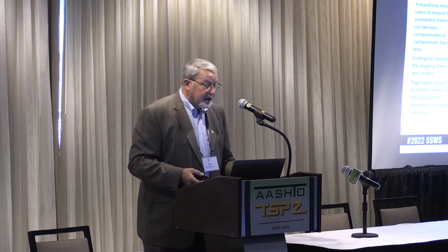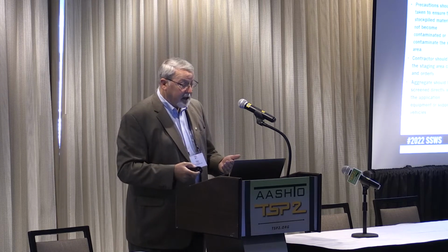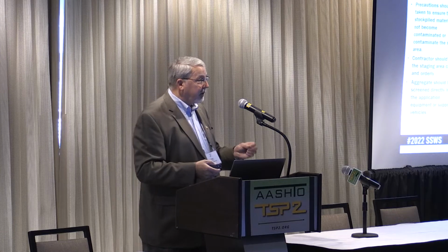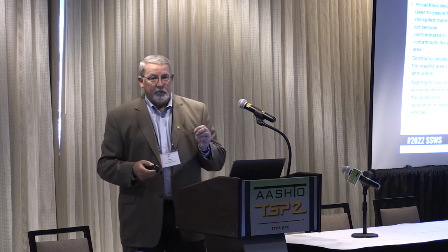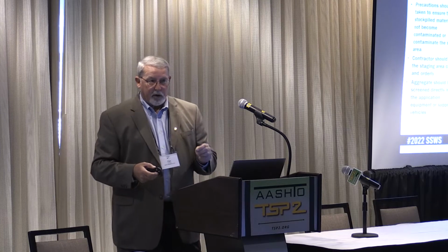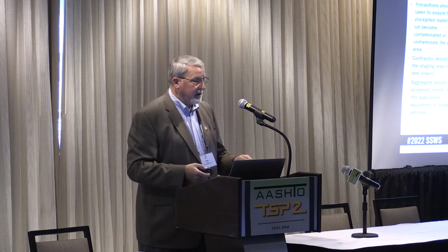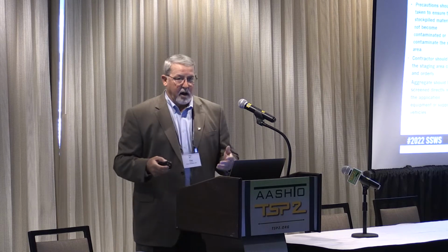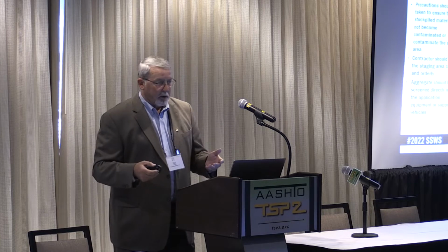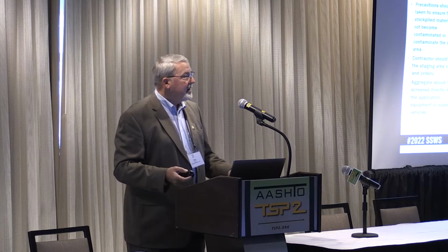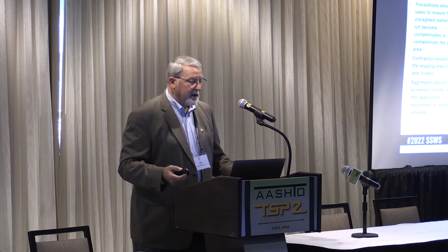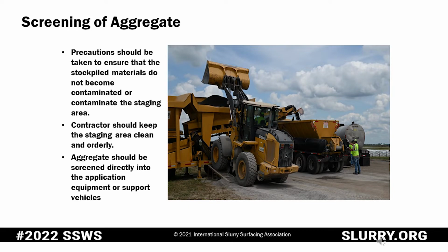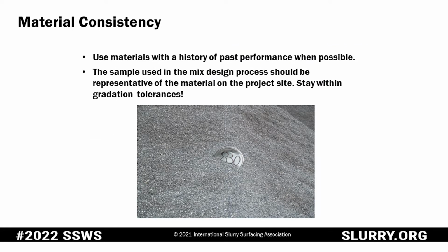Housekeeping's always a good issue, but ISSA, and we do it ourselves at Vance Brothers, we screen our aggregates directly in the nurse truck and/or the truck mounted unit prior to it going to the project site. If you screen it right back onto the ground, that just allows an opportunity for an overzealous loader man who gets too low to pick up some gravel from the underlying structure that your stockpile's on, and you've defeated the whole purpose of screening the stone. So screen it directly into your vehicles before they go to the job, and you'll save a lot of difficulties down the line.